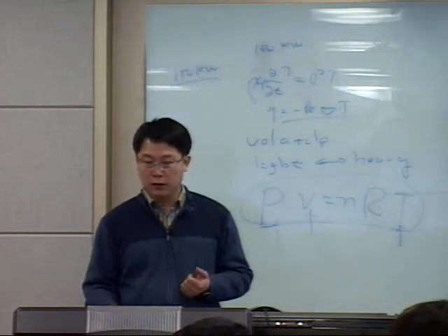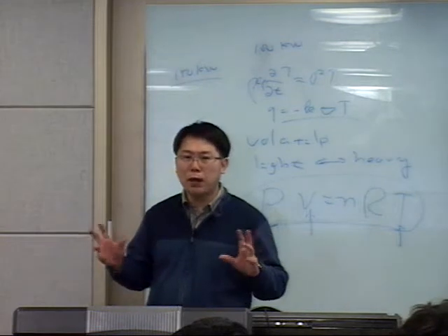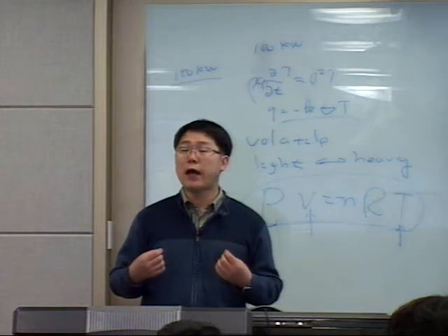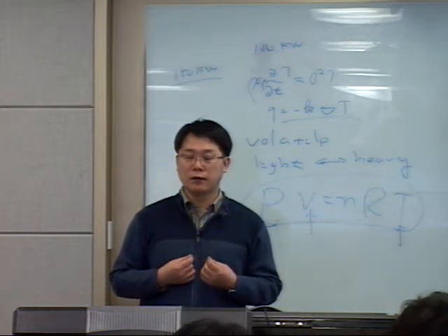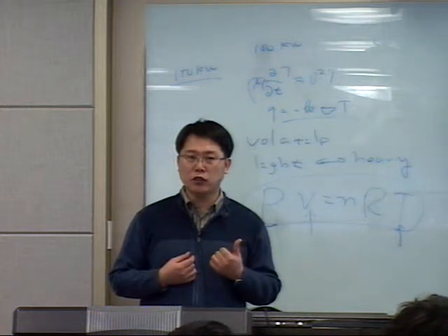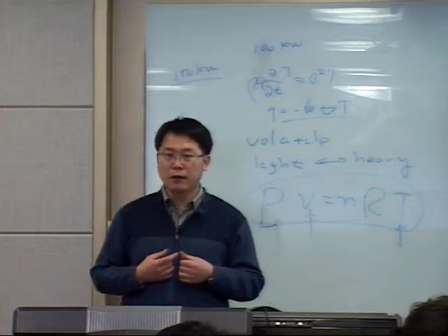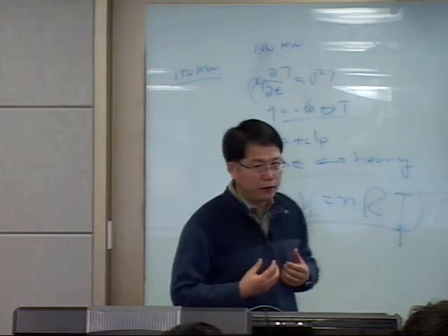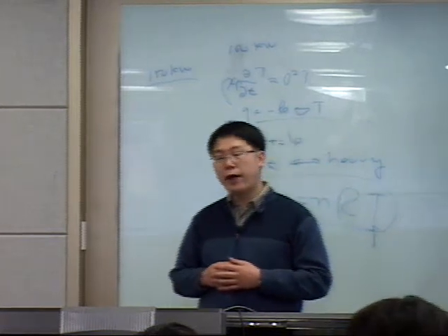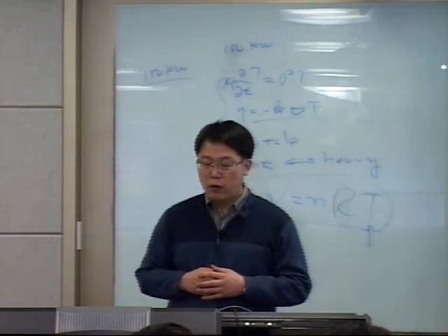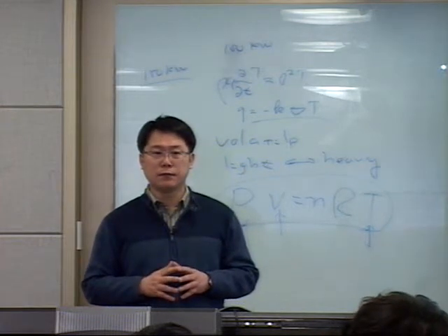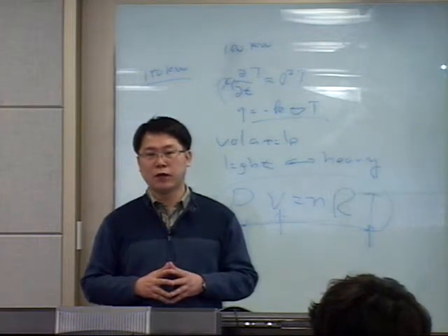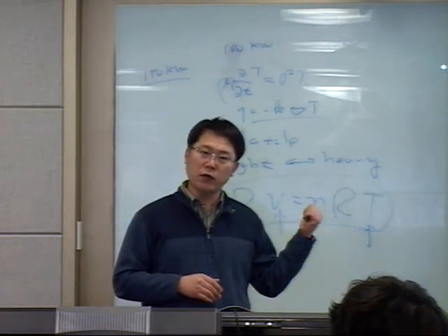So in this case, just think about the advantages and the disadvantages from the thermodynamic viewpoint. First example, PLNG, pressurized LNG. In this concept, we are trying to carry LNG at 10 to 30 bar. Then, what are the advantages of this system? We don't need to drop the temperature of LNG. Right, it's related to the boiling point.